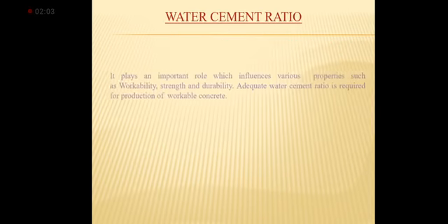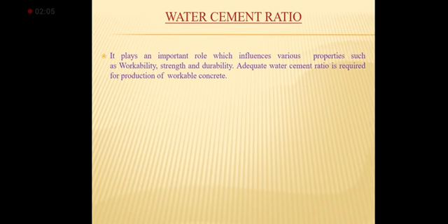What is water cement ratio? Water cement ratio is very important, as it influences various properties such as workability, strength and durability. It means the adequate amount of water should be added with respect to cement for production of workable concrete.